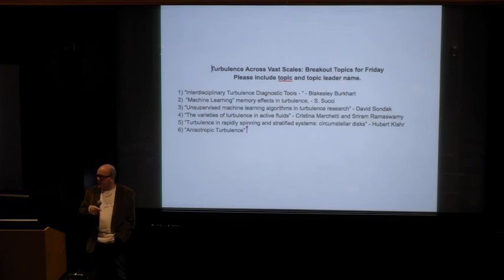So the stratification we have in our disk is not just affecting sedimentation, it's also a stratification which is on the same scales as your integral scale of turbulence. And this makes it really difficult, for instance, to construct a subgrid model, where you want to separate things. So if we would naively use a Smagorinsky model, then it would see, oh, there is shear, wonderful, and then produce a lot of viscosity potentially locally, and this might be wrong.